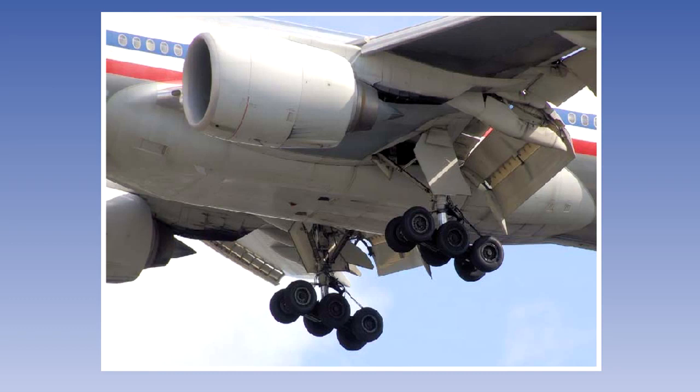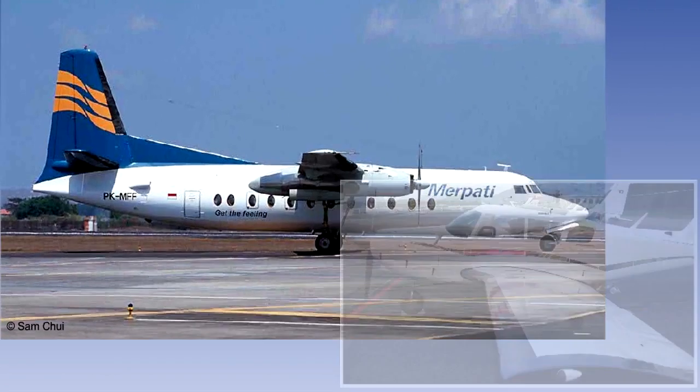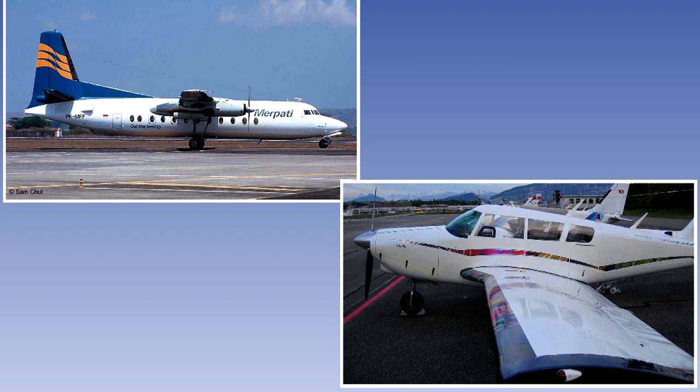In this lesson, we will look at the design and construction of retractable main landing gear. The majority of modern transport aircraft and an increasing number of light aircraft are fitted with a retractable landing gear for the simple purpose of improving aerodynamic performance by helping to reduce drag in flight. Operating power is normally provided by a hydraulic system, but pneumatic or, on some small airplanes, electrical systems are sometimes